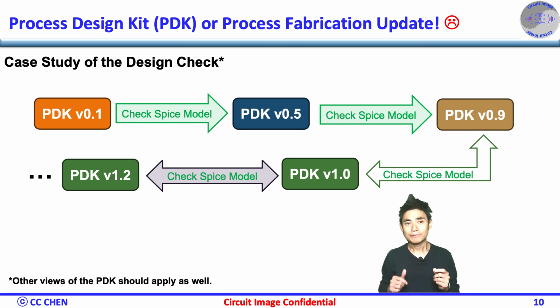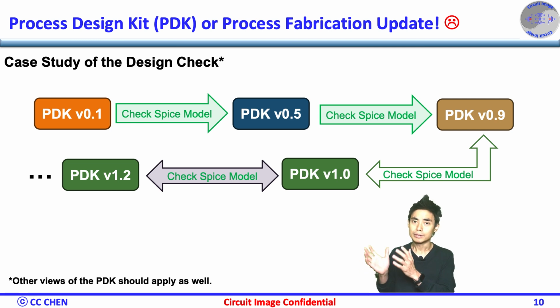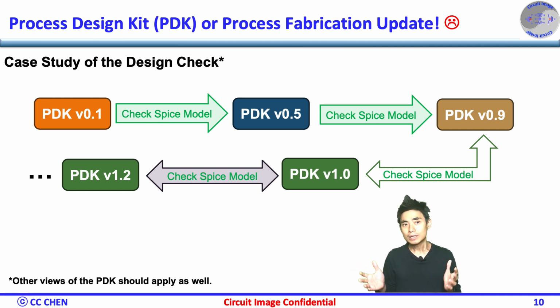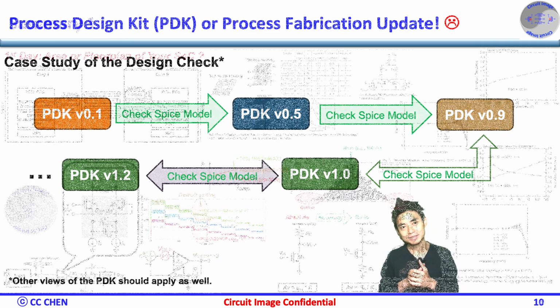Then you could have a big picture of how the impact is and contact the foundry if there's anything you could do or expect for the change based on further simulations. On the other hand, you could check the updated PDK and find that the change is little, and then you can relax with no need to run any simulation. So, the RLC process evaluation is a good spot check for the PDK update.